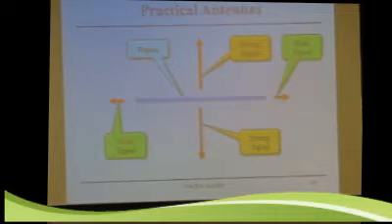work properly because you've got, I was trying to think if we showed this last week, you've got essentially voltage distribution like this, something like that, going all along the antenna. And that works out because it's balanced. If it becomes unbalanced, there are definite types of unbalanced antennas, but you get yourself into a whole host of problems that you don't have if it's a balanced antenna.